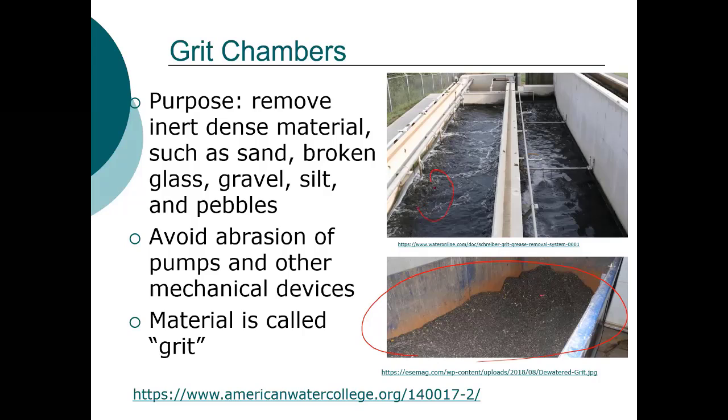The goal of this is to remove this inorganic material, the solid material, but keep the organics in suspension. So typically there's often a rotational flow in here. You can see that they're aerating this device, and that's to attempt to keep this organic material in suspension. And it's not uncommon that these are aerated devices. The grit is then typically disposed of in a landfill.